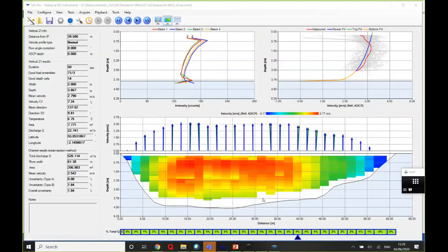The question that I had really about this, when you were asking Nick Everard, was that you would use stationary mode all the time. When wouldn't you use it? I was just wondering if you've got a change in depth that's changing quite rapidly, a change in stage, is that still good to use a stationary? Because obviously you could be taking half an hour, 40 minutes on a wide span to do a stationary one rather than 3 minutes, and the level can change quite a lot in that time. So I didn't know if that.